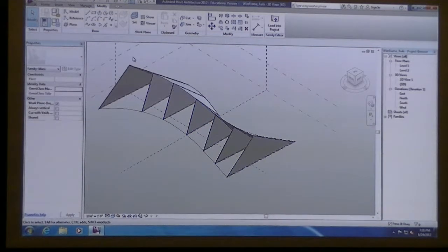Now we're going to do one last thing to that surface. In Revit, if we're just dealing with a surface, we can divide that surface up and then apply a pattern to it. This is going to be the same philosophy that we're going to use on your complex surfaces in order to make a tectonic structure follow your entire complex curves that you're currently working on. So this will be the first time I'm going to introduce this, and I'll go over it again a couple more times through different methods in following classes.